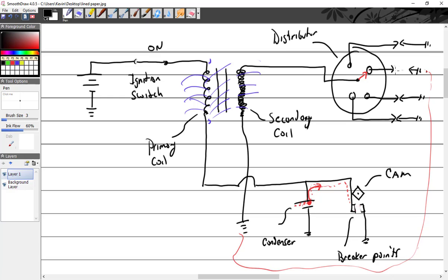And so what you're seeing is the yellow, the orangish spark. It's a very low voltage spark jumping the gap. Just very easily comes across. It's not a big deal. The blue is a higher voltage jumping the gap. So that's what's happening. You're seeing the voltage increase, and that's why the color changes. And you can see more molecules are smashed in there, so it takes more voltage to jump it. And that's why you actually put air on the spark plug when you're testing it, because you have to simulate what's happening in a cylinder.